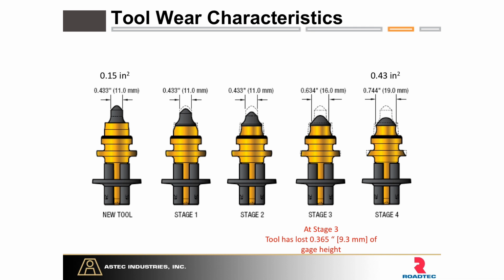This is a nice diagram of how the cutter teeth wear. As you know, the drum's filled with a number of teeth that actually remove the asphalt. Those teeth have a water system in the cutter housing. That's going to reduce dust. It's also going to reduce heat. As you would imagine, when these teeth are slamming into the asphalt, that creates a tremendous amount of heat. So in order to control that, they're spraying it with water, but also these teeth rotate in order to mitigate that heat that's created, because these things would essentially just burn down, melt away. They would wear in a very quick manner.